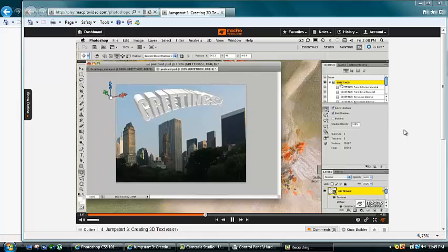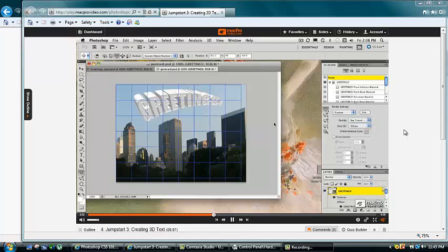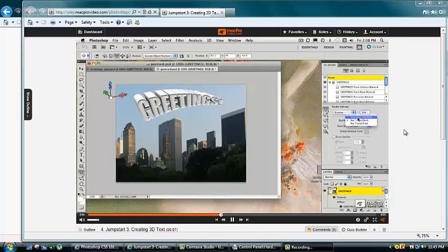Now if I go back to my 3D panel and choose Scene, here I can change the quality of the settings for rendering. It's currently set to Interactive, which is the fastest, and this is where you want it to be while you're modeling. When you're getting ready to see the final results, go to Ray Traced, and this grid indicates the areas of the pixels that the ray tracing engine is looking at to figure out how to redraw the 3D mesh. And you can see with ray tracing, we clean up the edges and now we get shadows. But for working, let's go back to simple Interactive.